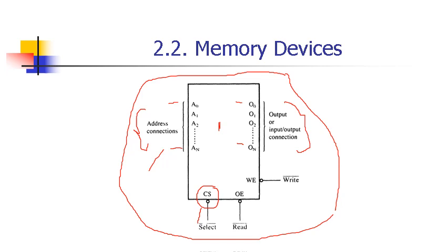If this type of memory is one you can read from and write into, you have to decide: are you reading a memory location from this device? If you are doing this, you have to supply a low signal to your output enable.